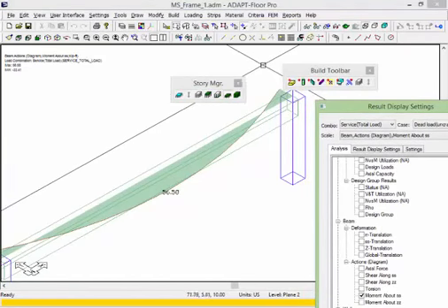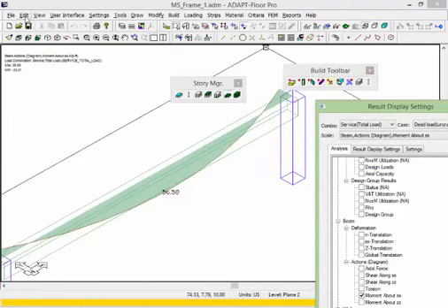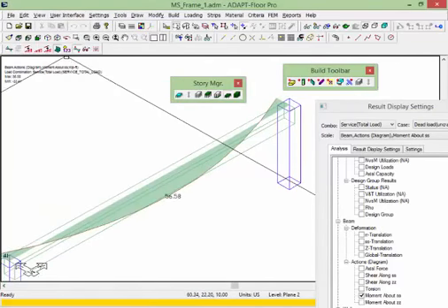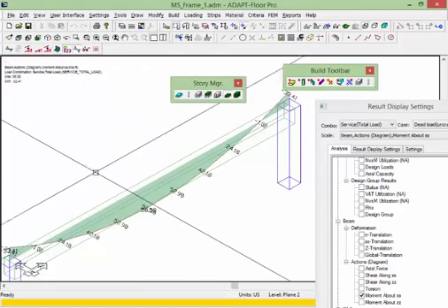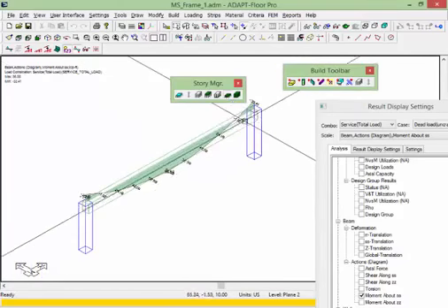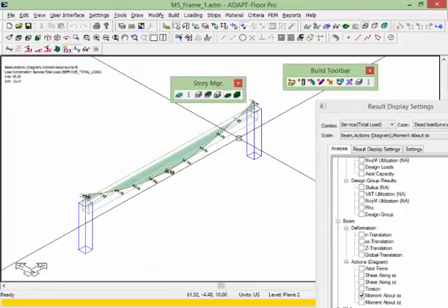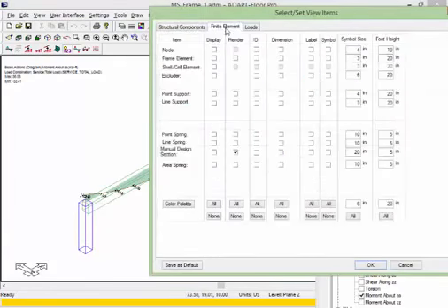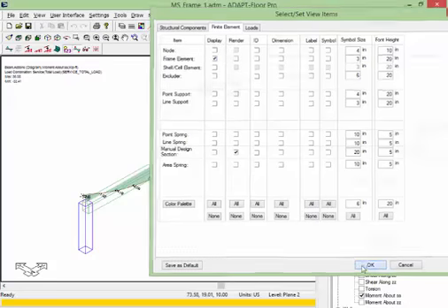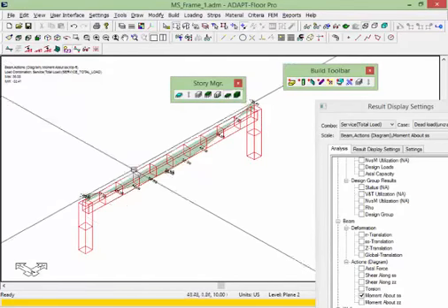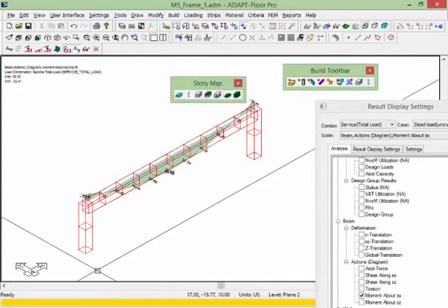And for this bending moment, let's go ahead and turn on the support line results toolbar. You can see the values here, and I'll also turn off the projected shape. This bending moment is relative to the beam frame elements. The beam frame elements can be displayed from select set view items, finite element, frame element. And again, this was subdivided into 4-foot chunks, so there are 10 frame elements along the length of the beam. There's 2 along the height of the column.